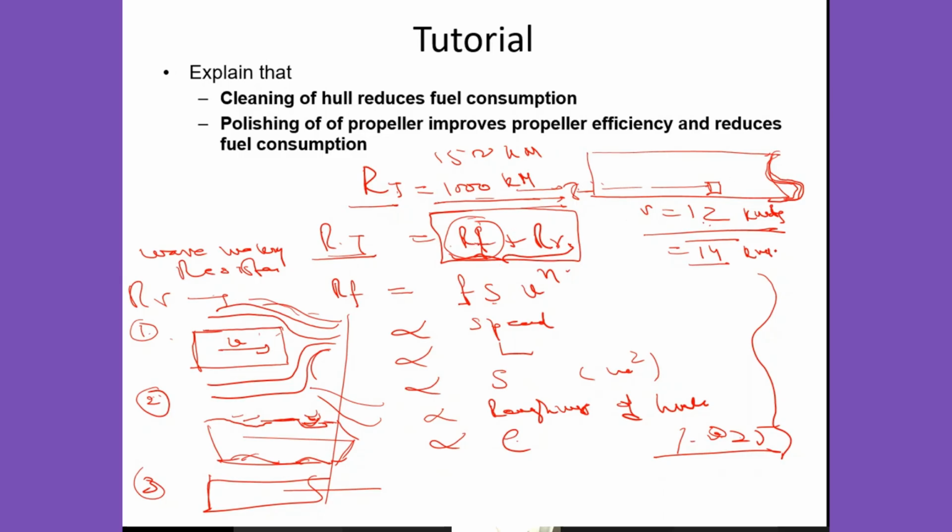But if I move the same vessel or a similar vessel at 20 knots, this 5 to 10% may become 15% or 20%, and it has been seen that at high speed it can go up to 60% of the total resistance. That means the frictional resistance is increasing linearly, whereas the residual resistance is in the form of a hyperbola, so it may become a larger portion of the total resistance. Obviously, the more the speed, the more the frictional resistance, but residuary resistance is not linear.